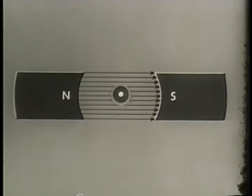The field of the conductor has the same direction as the main field above the conductor and the opposite direction of the field below the conductor. These two magnetic forces added together distort the lines of the main field upward. The field above the conductor is thus made stronger, and the field below the conductor is made weaker. So the conductor moves down.